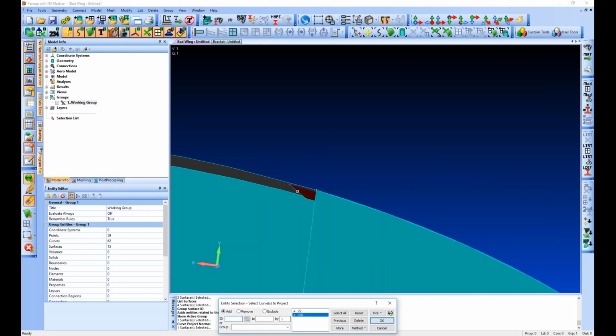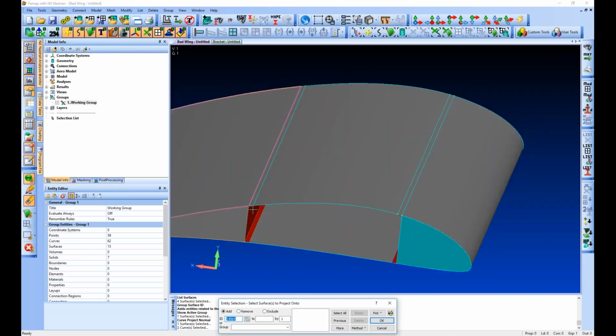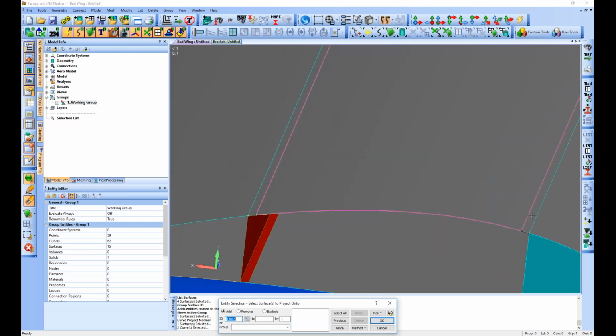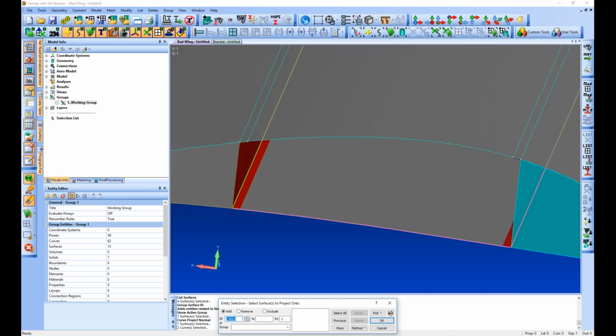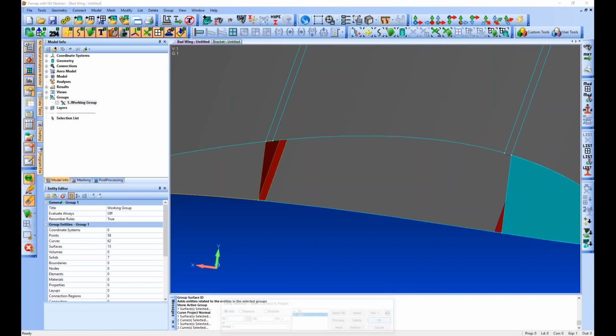our 2 curves. Those are going to shoot right up there, and you can see it's already split our surface into these small surfaces that we can mesh separately. We can make sure that there's a different fidelity mesh on there. This just gives us more control over the area. And we'll repeat the same thing down here.